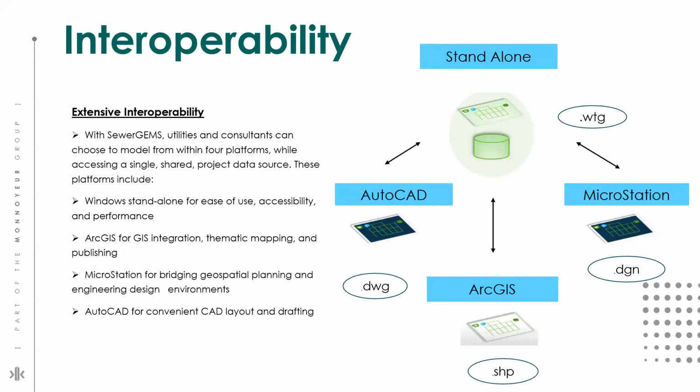Then we have AutoCAD as well. The AutoCAD mode lets you create and model your network directly within your primary drafting environment. This gives you access to all of the AutoCAD drafting and presentation tools while still enabling you to perform Bentley SewerGEMS Connect modeling tasks like editing, solving, and data management. This relationship between Bentley SewerGEMS Connect Edition and AutoCAD enables extremely detailed and accurate mapping of model features and provides the full array of output and presentation features available in AutoCAD. So these are the 4 major platforms where we can actually integrate our data within SewerGEMS Connect Edition.